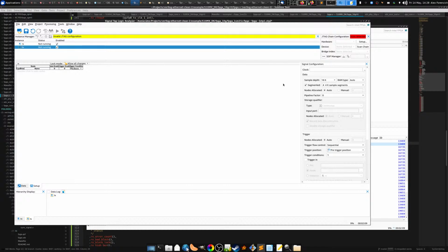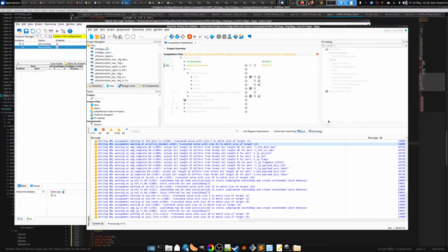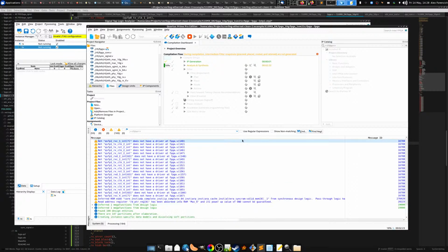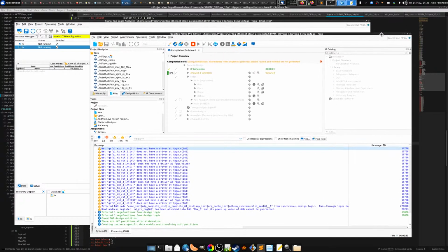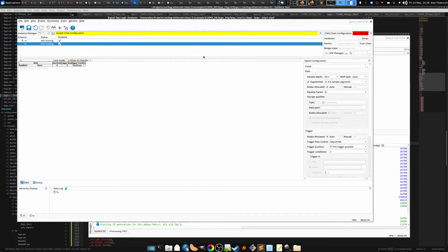Because you might be running at a few hundred megahertz. If you want to hook up an external logic analyzer at a few hundred megahertz, I mean, one, you need a lot of pins, and two, that's a pretty major signal integrity challenge to make that sufficiently reliable. So being able to make all this stuff work internally without having to consume a bunch of IO pins and deal with all sorts of annoying signal integrity, and being able to run really wide interfaces is very useful.